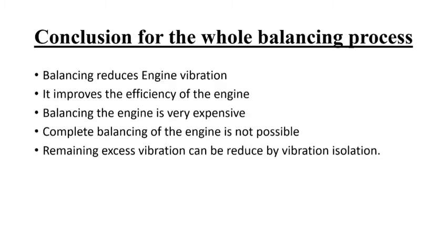Now let's check the conclusion of the whole balancing process. Balancing reduces engine vibration. It improves the efficiency of the engine. Balancing the engine is very expensive as we need to deal with some geometric parameters which are to be pretty precise. Complete balancing of the engine is not possible. Remaining excess vibration can be reduced by vibration isolation.